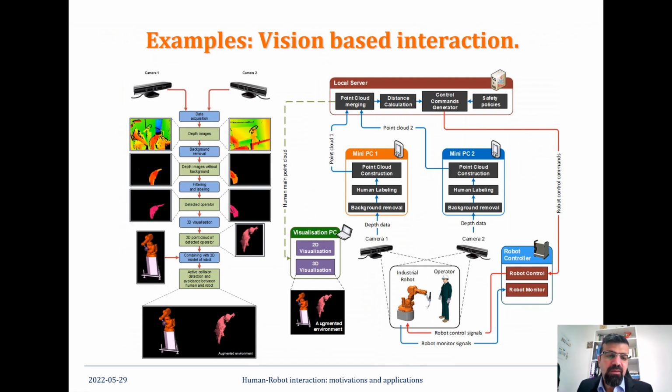On the other hand, the sensors in the joints of the robot can be used to construct a 3D representation of the robot and merge it with the point cloud to create an augmented environment where we can monitor both the human and the robot. We calculate the minimum distance between the human and the robot to facilitate this interaction safely, without any injuries or collisions.